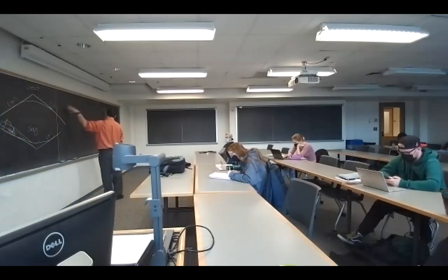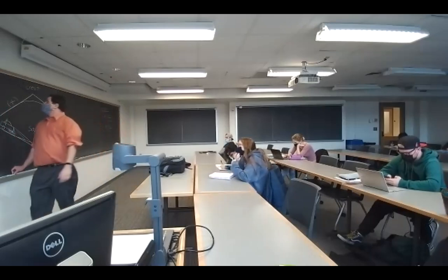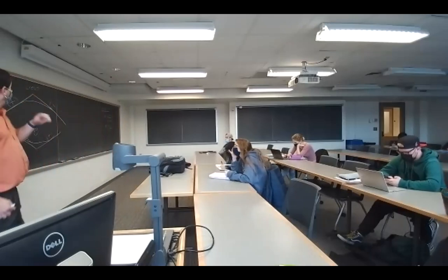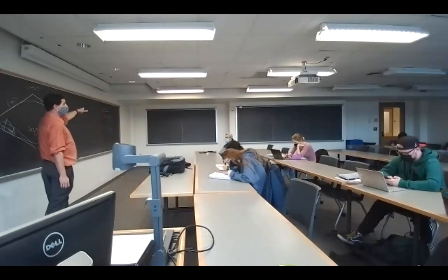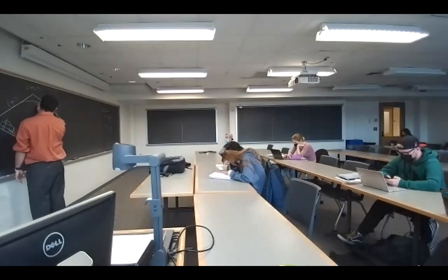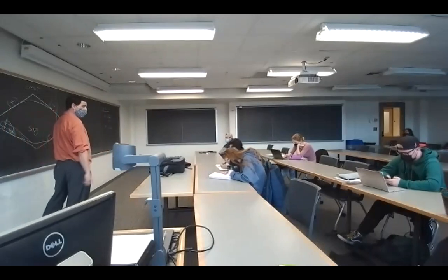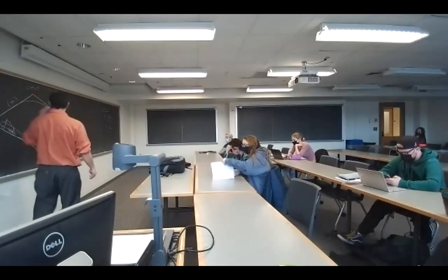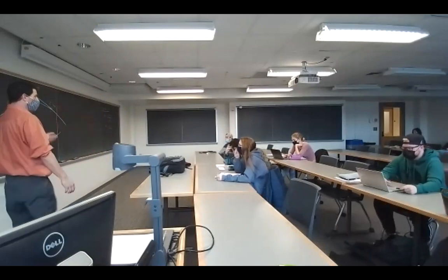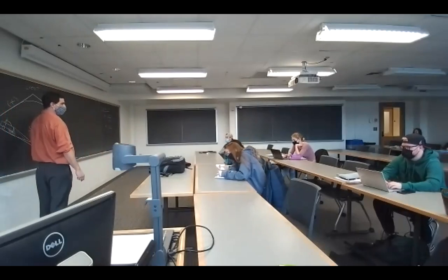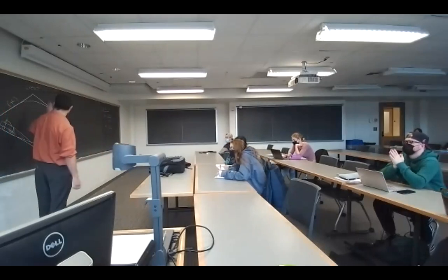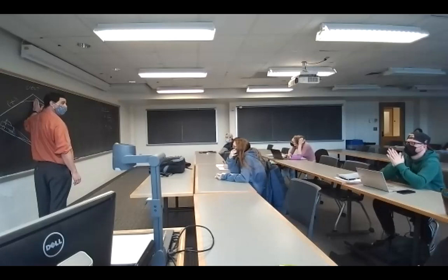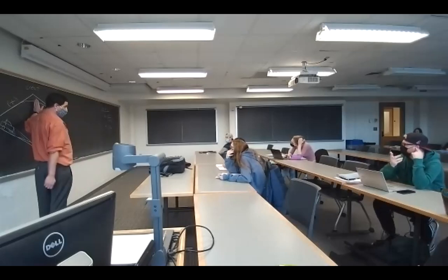The reason that's important is because it leads us to the high point and low point. So depending upon the grade going in and out is going to dictate where this high point or low point would be. If I've got an equal grade going in and going out, and it's an equal tangent vertical curve, where is it going to be? Right in the middle, because it's the same going in as going out.